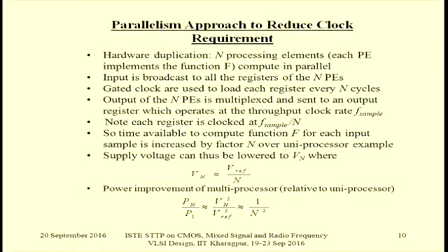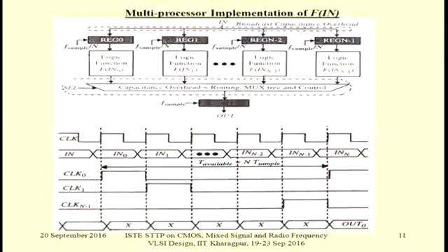An n-bit ring counter means that the clock for each output of different stages is valid only for a single clock period. So if you have, say, a 4-bit ring counter and a 4-stage parallel circuit, then to each circuit you can apply the gated clock, say Q1, Q2, Q3, Q4. That is what we are doing.